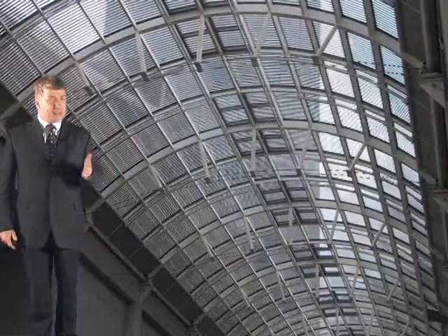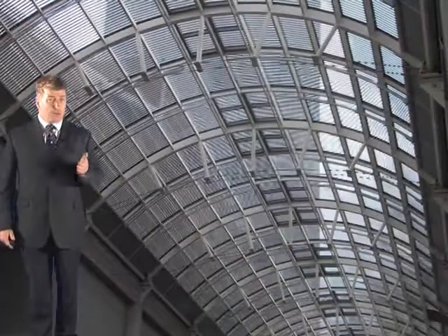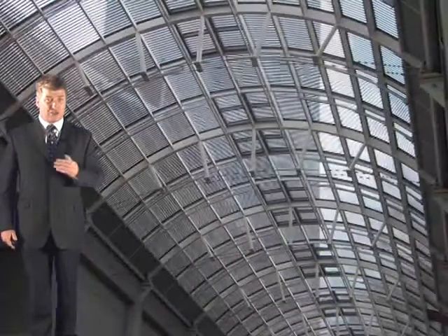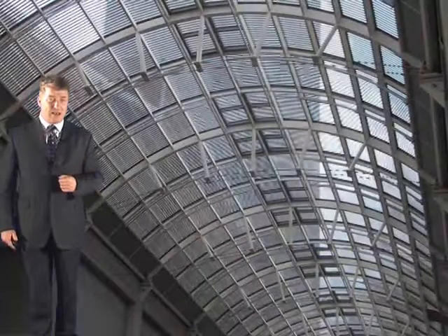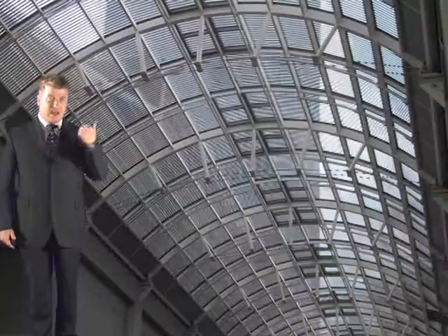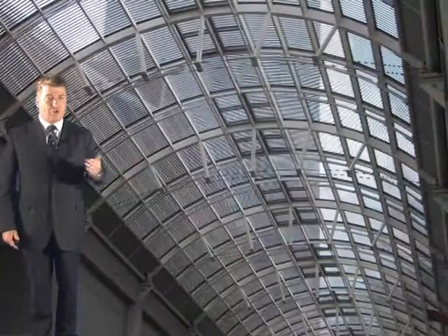Now, for example, cases have been witnessed recently where smoke vents have been sealed shut because they've started to let the rain in, and no one thought there was a problem by sealing them off. No one actually thought, what functions are they intended to perform? And in another situation, smoke curtains designed to drop on the local detection of smoke have been sealed in their housed position because of false alarms and problems with rehousing them.